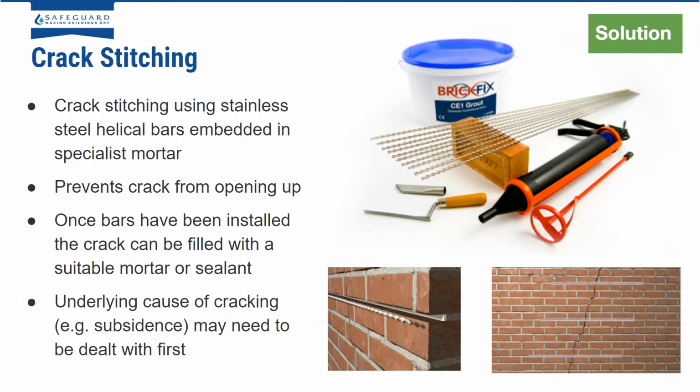So in a situation where you have got large cracks, materials such as Brick Fix can be used. So that's the helical bars, for instance, and the grouting can be used. Can be embedded with a specialist mortar to stop any movement cracks within the wall. So once the bars have been installed, the crack can be filled with a suitable mortar or sealant. But be aware that the underlying cause of cracking, such as subsidence, should be rectified first before doing this work.